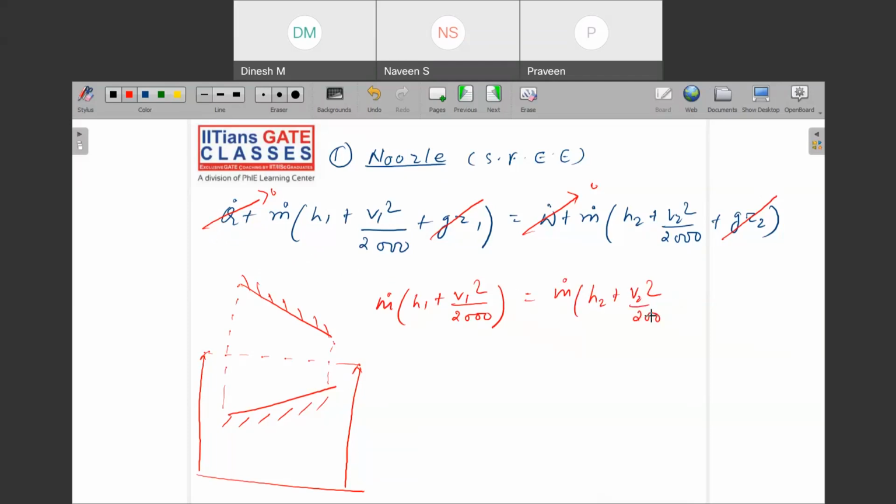So can you see that if you are not aware how to sort, means eliminate the unknowns, then you will be in a difficult situation. Okay. Then can I see that nozzles are used to increase the velocity of the fluid passing through them. So in general, if they do not mention even the entry velocity, but if they are providing you the data, you use it. And if they have not provided it, what you will do, directly 0.